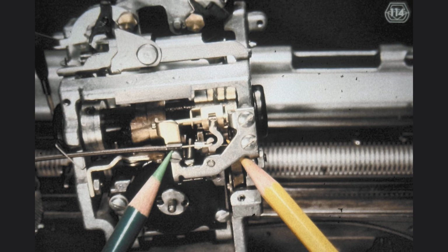Before we reinstall the carrier, take a good look at the parts of the printing mechanism. Here, for instance, the yellow pencil shows the roller of the print cam follower, and the green pencil points at the anchor spot for the shield or tube of the velocity control cable. You should examine in detail how the print cam follower is pulled towards the left, into the path of the low velocity lobe, and how it is restored back towards the right after the printing of a low velocity character.